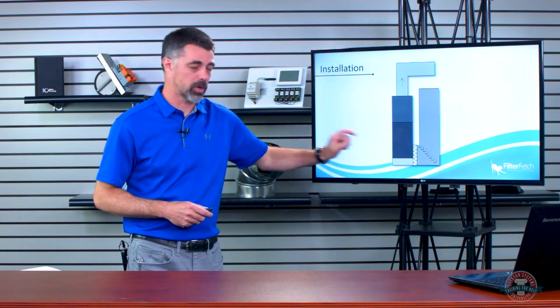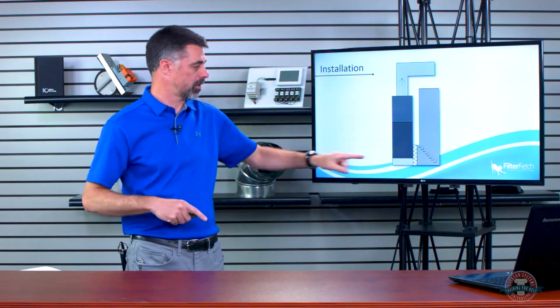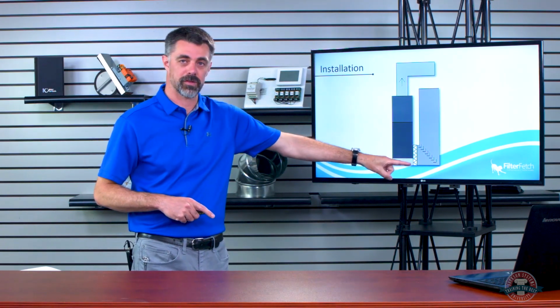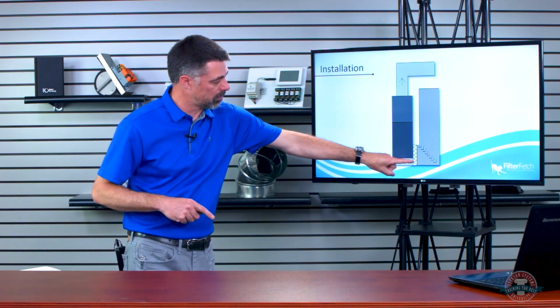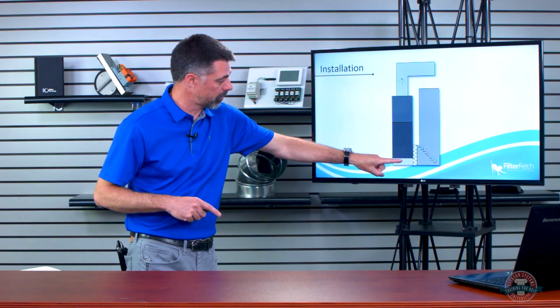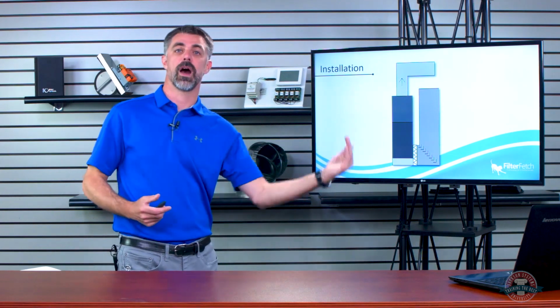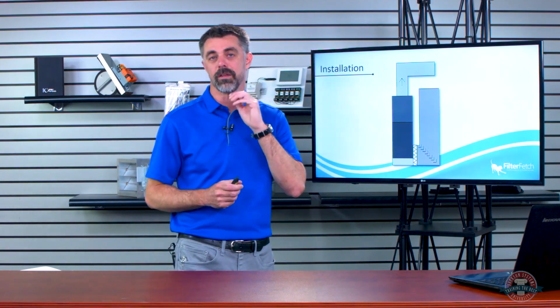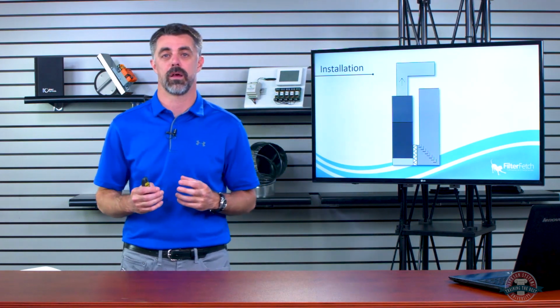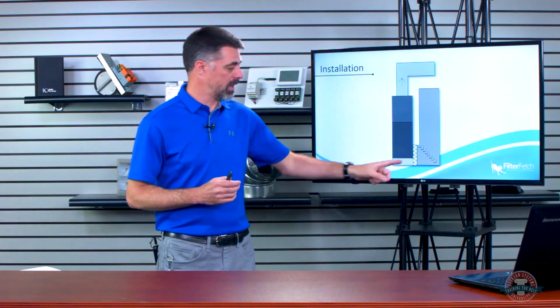So we can put a short box underneath that furnace, and we cut out the side of the furnace and the side of that box, and that allows the air to come across into the blower, and some of the air comes across the bottom of the blower and can feed the opposite side of that blower. This is really important, and make sure you look at your manufacturer instruction manuals, because a lot of manufacturers want the air coming in the bottom after you get above a certain tonnage on gas furnaces.